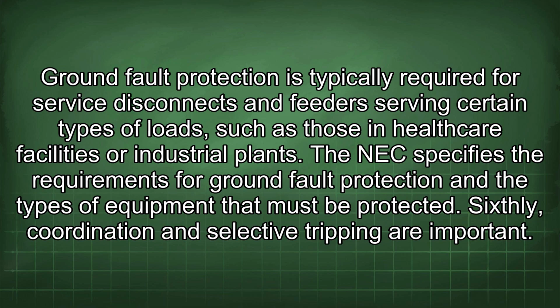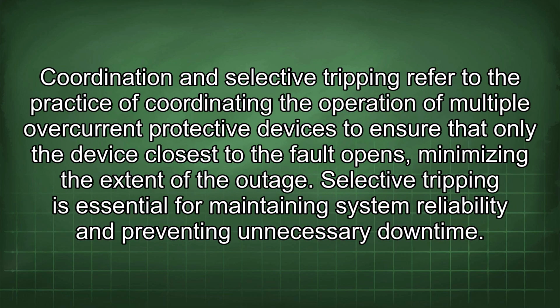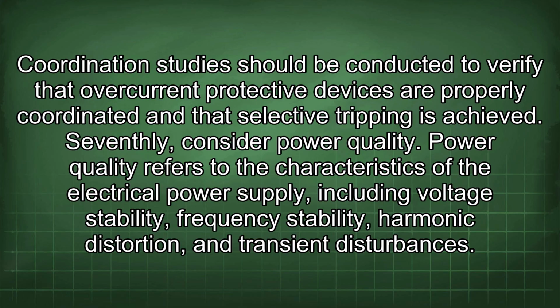Sixthly, coordination and selective tripping are important. Coordination and selective tripping refer to the practice of coordinating the operation of multiple overcurrent protective devices to ensure that only the device closest to the fault opens, minimizing the extent of the outage. Selective tripping is essential for maintaining system reliability and preventing unnecessary downtime. Coordination studies should be conducted to verify that overcurrent protective devices are properly coordinated and that selective tripping is achieved.